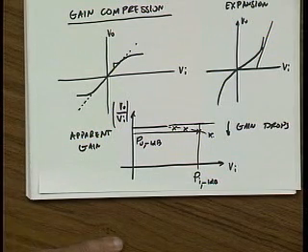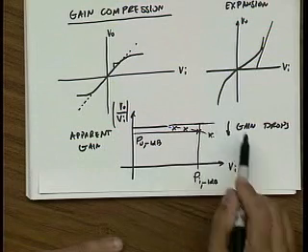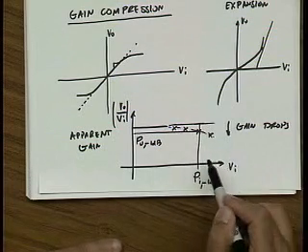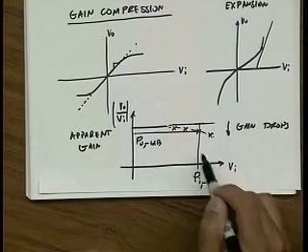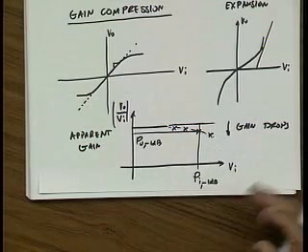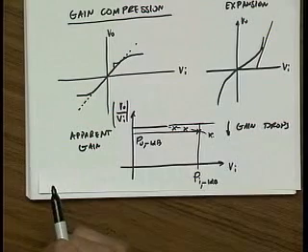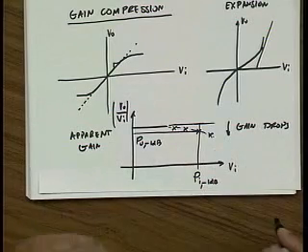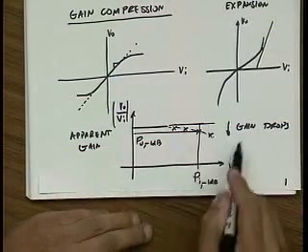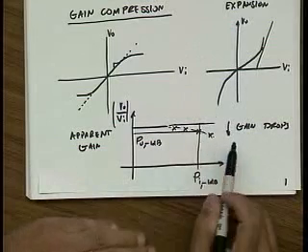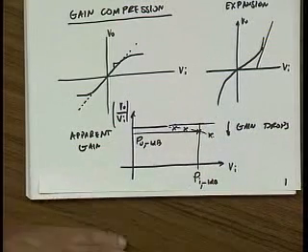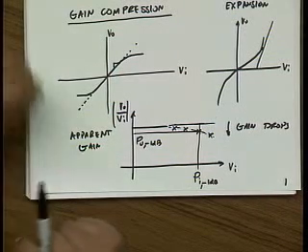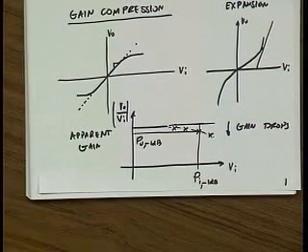compression point. Now the reason that we don't like to operate an amplifier beyond compression will become very clear in this lecture. So it might seem, sure, just use an amplifier out here, you're going to get less gain, but it's still a good amplifier, right? No. We'll see today why we don't want to use an amplifier in this region. So well below the 1 dB compression point, that's the small signal region where we like to operate an amplifier. Okay. Questions or comments?